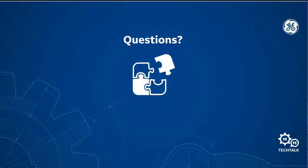Here's a great question. What is the basic data we should ask the customer when a fault is reported, and from which data should we start investigating? So what data do you need to investigate? Well, one of the best pieces of data that you can get from the field to start an investigation is a service report. On all of the GE devices, when you're connected to a relay, you can get a service report from the device.